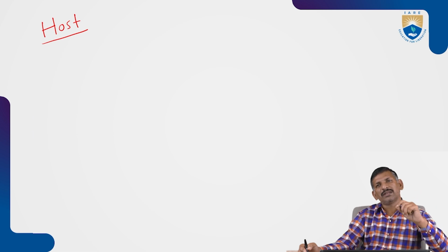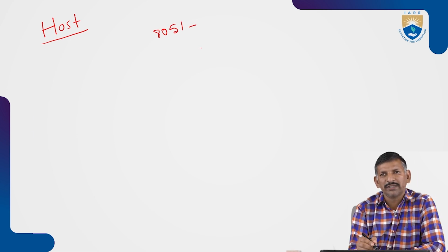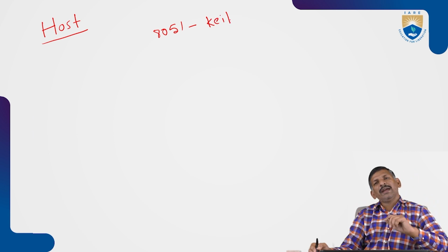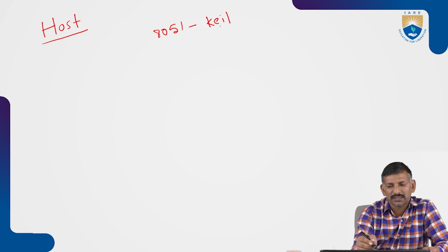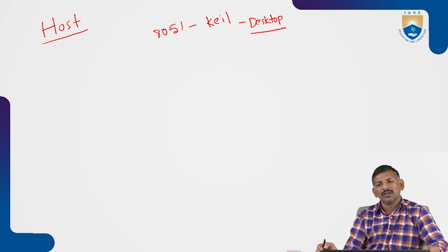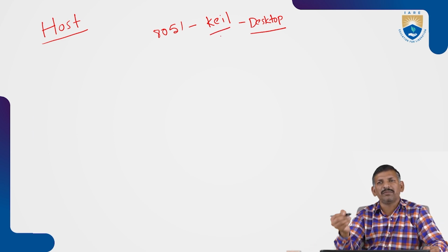Based on the processing element, the supplier or manufacturer provides the corresponding IDE tools. Suppose I want to design applications on an 8051 based processing element. The manufacturer, Intel 8051, provides the Keil IDE tool. This Keil IDE tool is installed on the desktop computer. So here the desktop is the host machine. On this desktop, I install the Keil IDE tool and design my requirements.